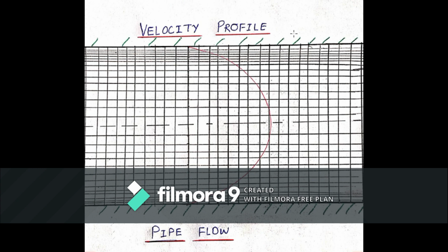For the purpose section, we will take an example of the parabolic profile of velocity for a laminar case. I have divided this into small domains. These domains would serve the purpose of capturing the gradients of the velocity. So let's say I choose a very small domain near the wall, a very fine domain, and in this domain you can see that the curve is exactly like a straight line, because we have a very small domain and the curve behaves like a straight line.